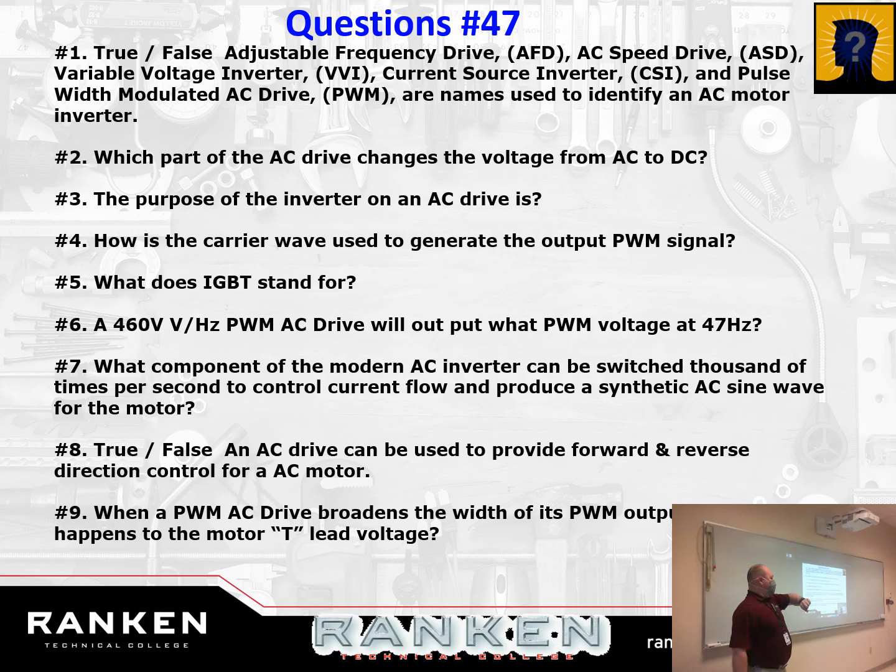Alrighty, thank you. When a PWM AC drive broadens the width of the PWM output, what happens to the motor T-lead voltage? So when that pulse gets wider, or they leave it on longer, what happens to the T-lead voltage? It goes up, or it gets stronger, or higher, whatever way you want to put it.